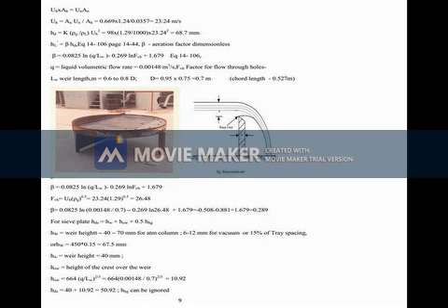Then assume that AD is the downcomer area, 10% of AT. So you can find out the AT, that is AN plus AD is equal to AT. So the relationship of AD and AT is 0.1. So you get AT as AN divided by 0.9. You get 0.7744. Find out the diameter using, for a circle, pi by 4 d squared, d is 0.973. And the downcomer segment area I am leaving for the time being.